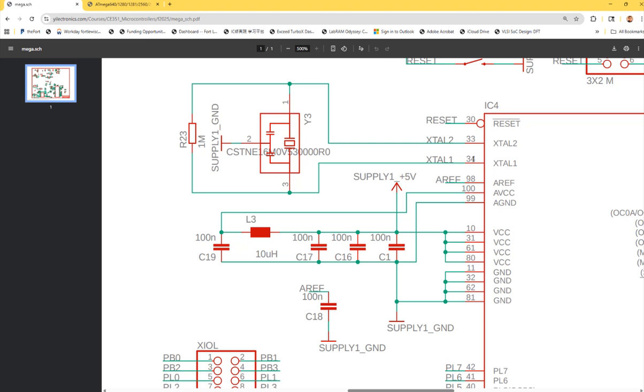Right? If it only has 1 UART, we put a UART into the USB and trying to look at the serial monitor, we won't be able to perform any IR transmission. So that's why we decided not to use that Uno board. But it's okay as an educational product. It's fine.